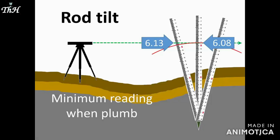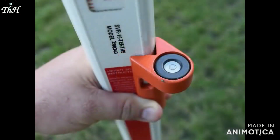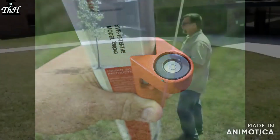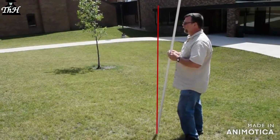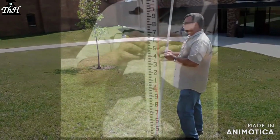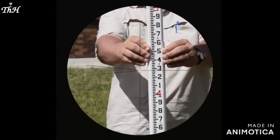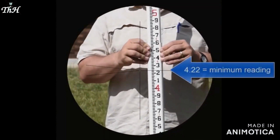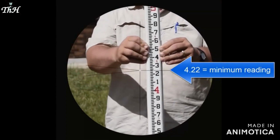There are two common methods. First, this small device, often called a rod level, when held against the rod, uses a circular level vial to indicate when the rod is plumb. Second, if you don't have a rod level, you can rock the rod smoothly back and forth in the direction of the instrument. As the rod passes through the vertical position, the instrument operator will see the reading reach its minimum value momentarily. To ensure the rod is vertical relative to the instrument operator's left and right, stand behind the rod looking toward the instrument.